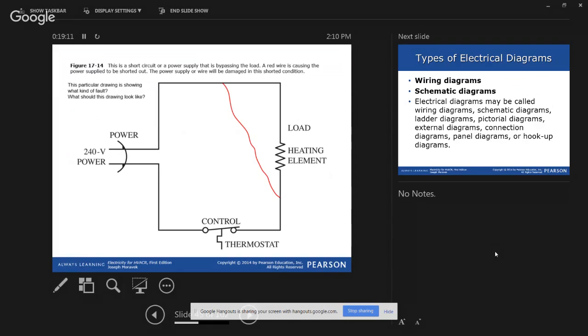So if you grab your meter, you stick it on this voltage here. Here's a meter point, and you take it over right here. Whoops, excuse me. That ain't right either. So you take your ohm meter out, switch it over to ohms, and you read from this over to this coil. You should have a very high resistance.